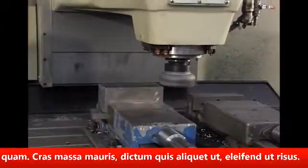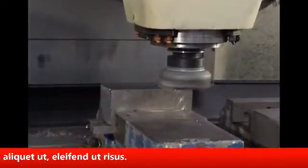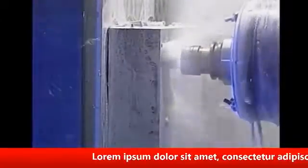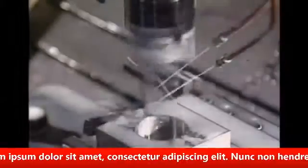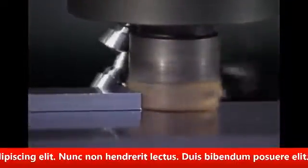As an introduction, we've covered only a few of the many aspects of milling with carbide tools. Extensive calculations are also involved when choosing effective cutter types, cutter paths, and cutting parameters. Let's re-examine the material contained in this videotape. Cutting tools cut with an edge, and those edges can be described by their geometry. For metal cutting efficiency, it is critical to select the edge that cuts best, given the material and cutting conditions.